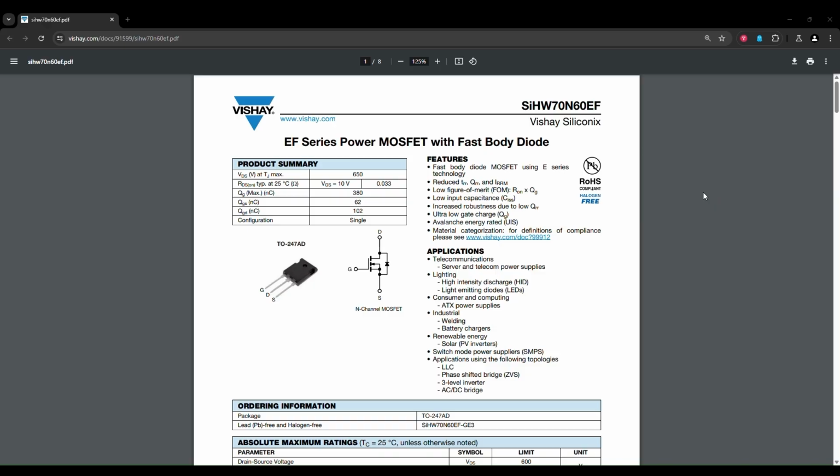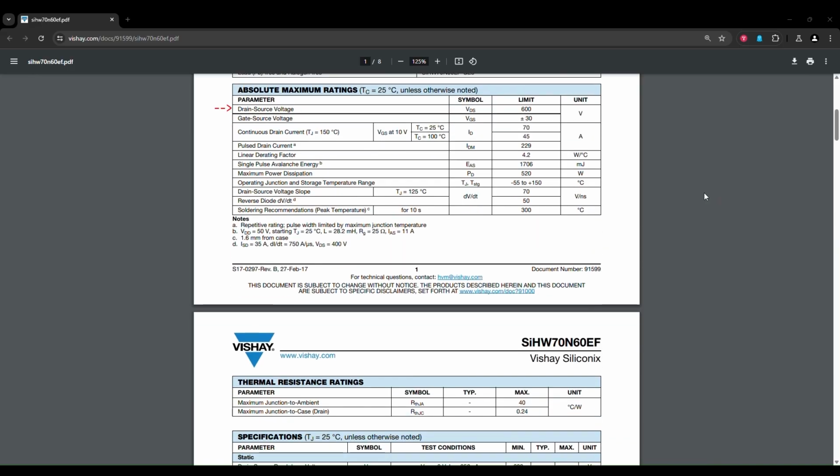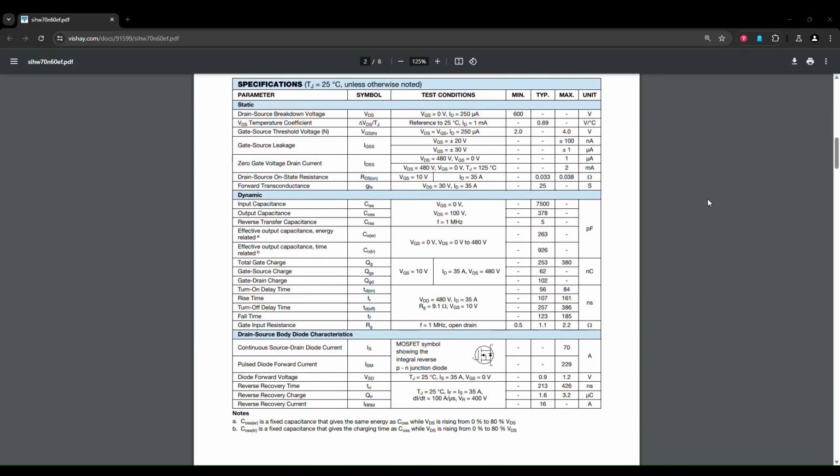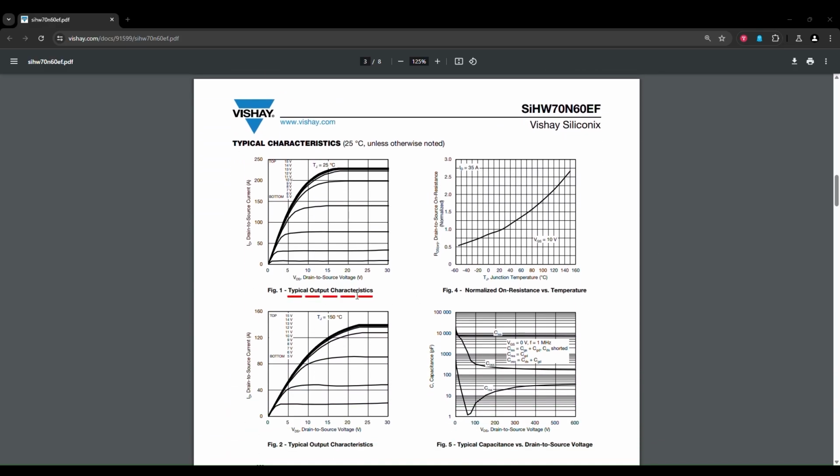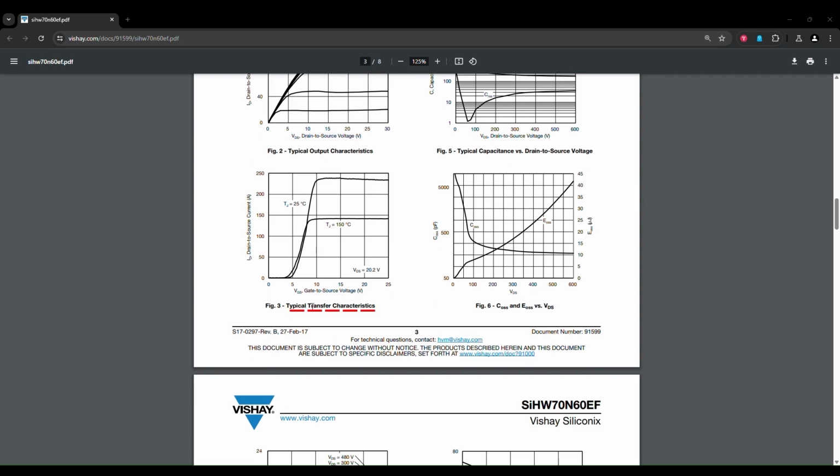This is the datasheet for a Power MOSFET. Scroll down to locate the various parameters, which directly correspond to the entries in the MOSFET modeling app. We will use the MOSFET model to simulate both the output characteristics and transfer characteristics that are typically illustrated in the datasheet.